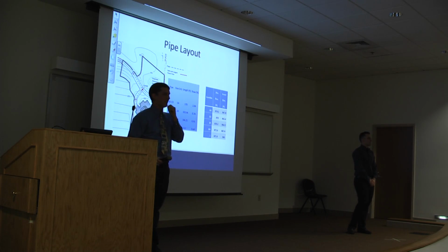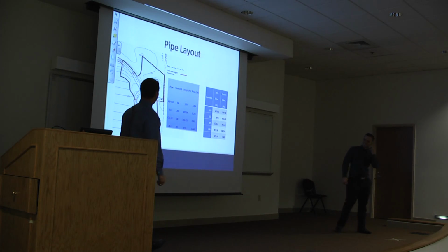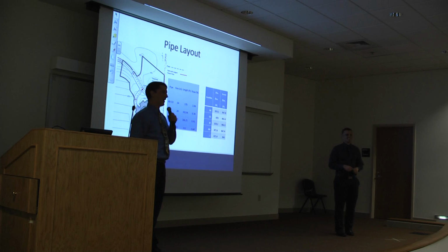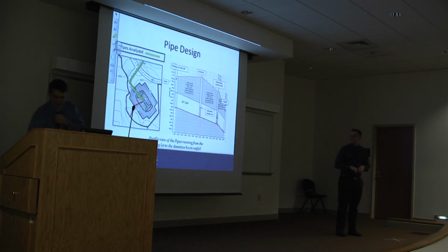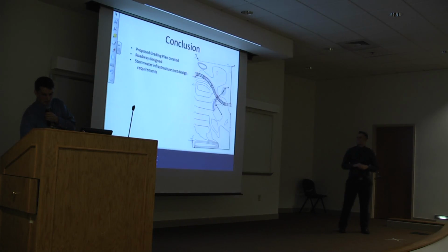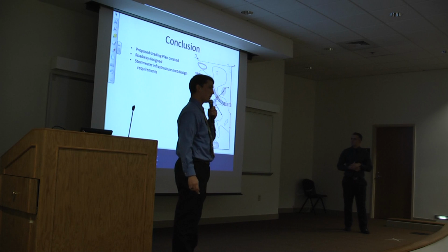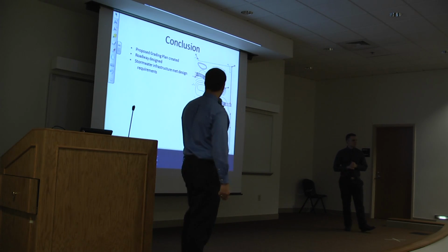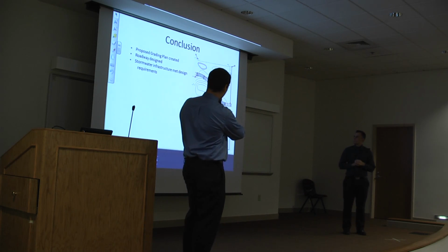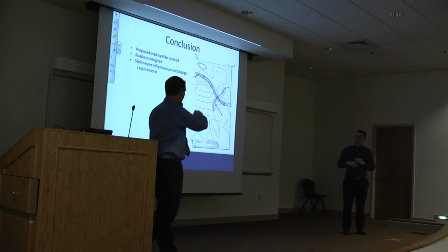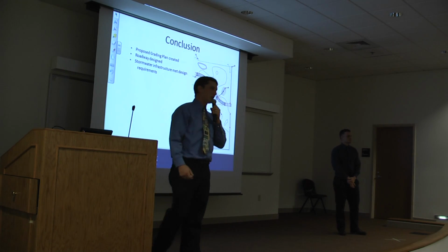So what did you guys do about the detention on the bottom compared to the side? You're talking about this detention basin here? Okay, so you did design it. Yeah, we're proposing a detention basin in the top left and a detention basin down in the bottom for the water running from the multi-sports field to collect down in the bottom of the site.